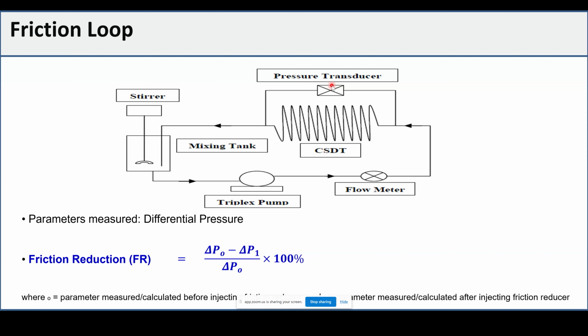So we run this test typically between 4 minutes up to 10 minutes, depending on how much time you are pumping inside the field, meaning how much time the fluid takes from the surface to the perforation. If it takes 4 minutes, you are doing it maybe for 5 minutes, with some additional time. If it takes 6 minutes, or 10 minutes, you do it similar to the time that you expect it to go from the surface to the formation, with some sort of additional time frame.